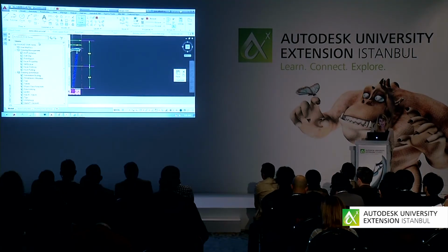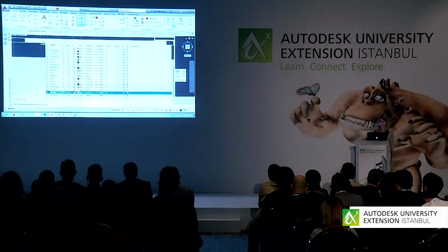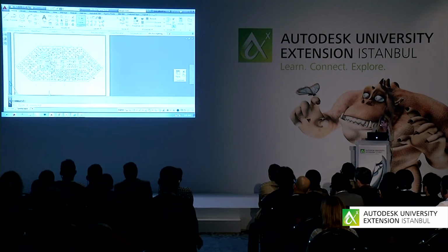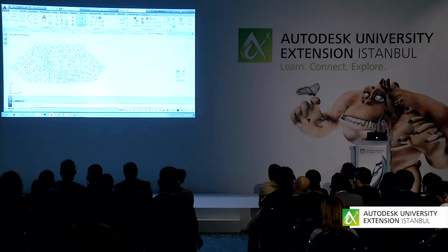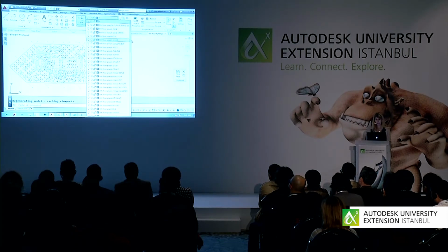If you've ever had a drawing where the objects were not on the right layer, they were not by layer. If you ever took an AutoCAD class, you're told the importance of setting things to by layer. If you take a look at my layer list here, you can see that everything is gray.